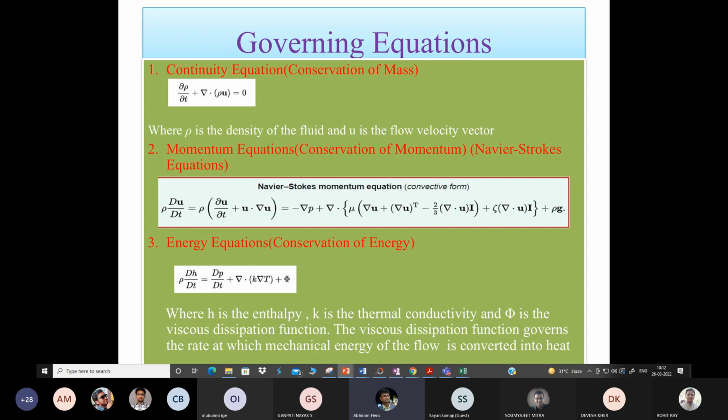Okay, so we are fixing a control mass and based on that we do our treatment. But in case of fluid mechanics, it is always useful to take a control volume approach. Control mass approach means, let's say this is a body, its mass is fixed. Now, if it moves from here to here, you are targeting that this mass is fixed, which is moving from one place to another, and you can do the necessary analysis.